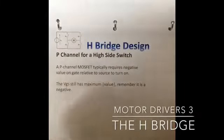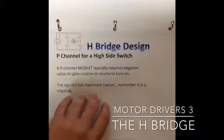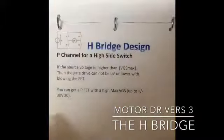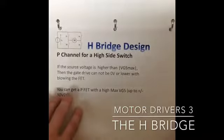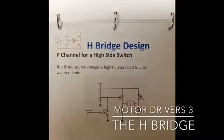For P channels, it typically requires a negative voltage, but that's just relative to the orientation of the switch. The VGS has a maximum value. Remember, it's negative. It's still the same concept. If the source voltage is higher than the VGS max, then the gate drive cannot be 0 or lower without blowing the FET. You can get a PFET with a high max VGS, like plus or minus 30 volts. That would help solve the problem. But if your source voltage is higher, you will need to add a Zener diode in something like this configuration.